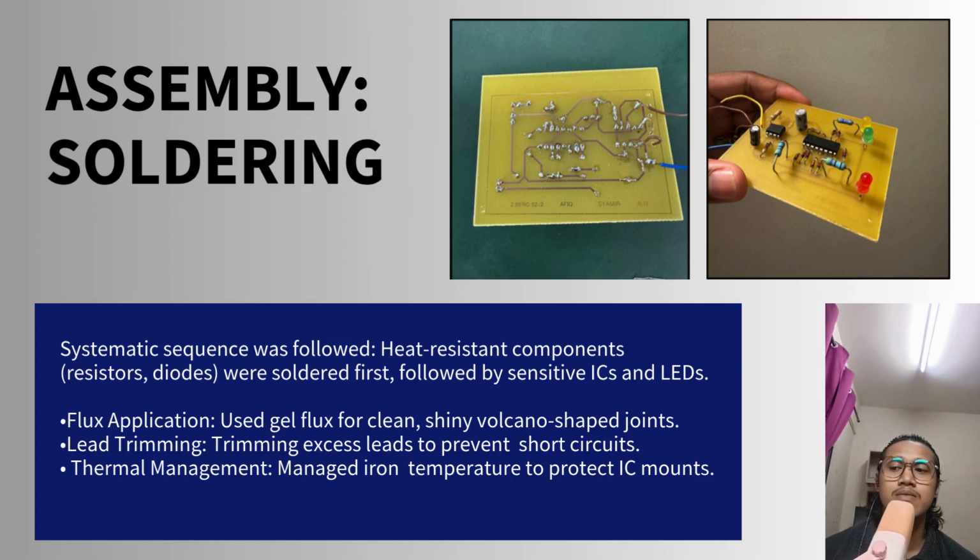We were given gel flux by our lecturers, which is to produce clean and reliable solder joints. After that, we also controlled the temperature of the solder to avoid damaging sensitive electronic components.